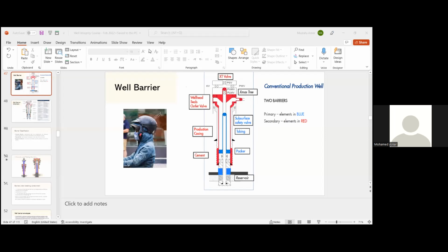And if you want to keep the well as it is, it's just water between the two casings. You just keep the pressure in the annulus as it is. If you bleed this fluid, it will enhance and induce more fluid production between the two casings. And if you let the pressure build up above the maximum allowable pressure, it will be a problem.